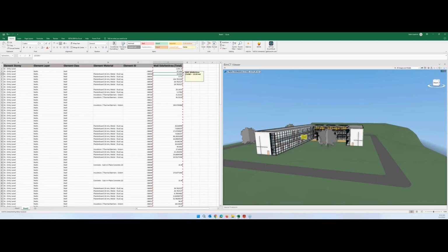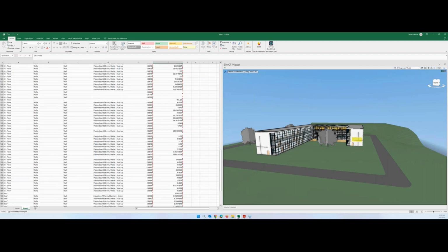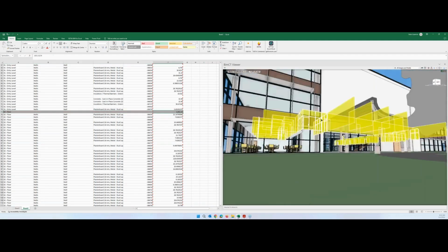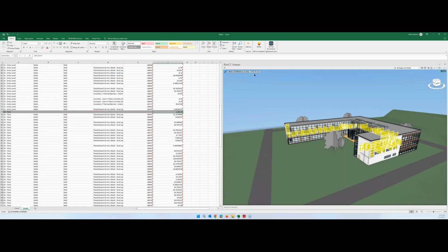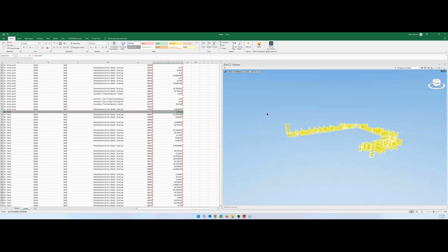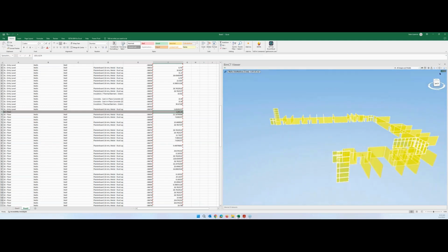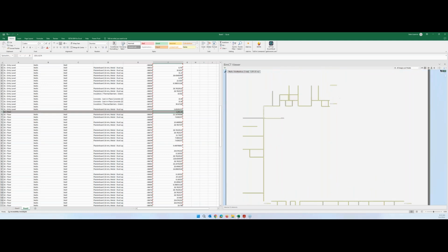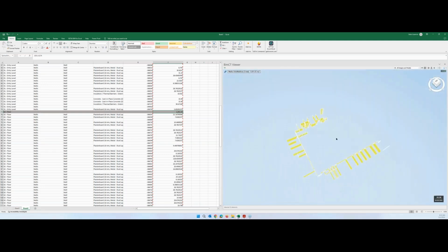So now I have the total quantity for the first floor. I have the total quantity item by item. All the walls are selected here. So for any items, I go, for example, to the second floor, and these are the second floor items. In summary, you can make it here. When you select it, it's just showing the second floor walls. So just the display total 1051 square meters. Right click, hide other elements, and you can see that all the second floor walls are selected here. So this is how we are able to also open all the selected items in 2D or in 3D.